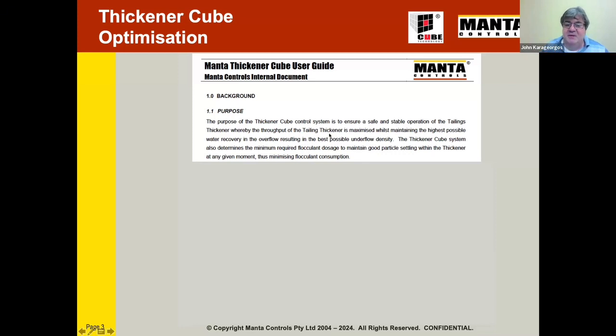And by doing that, you also want to maintain the highest possible water recovery, or liquor recovery if you're in a CCD washer environment, which also means a thicker underflow density. So you can think of them either way.